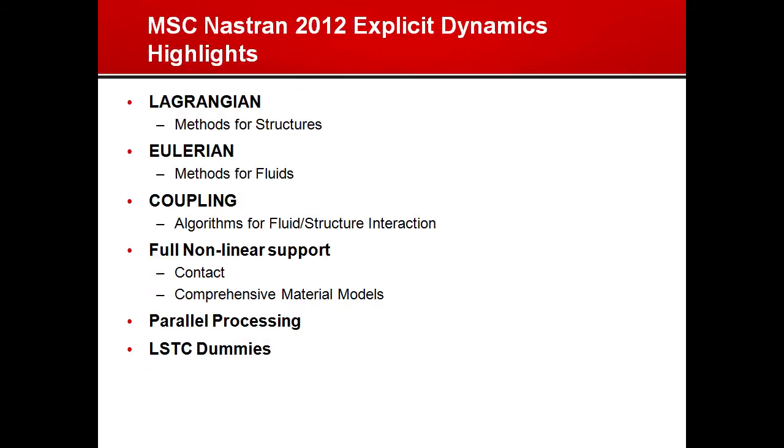So from a high level, within MSC Nastran we've got Lagrangian, typically used for structures, and Eulerian, typically used for fluids, and those fluids can have strength, which allows us to simulate structures with a fluid representation. We have some very powerful technologies that we call coupling that allow you to couple the Lagrangian and Eulerian solvers together and have an interaction between that fluid and that structure. That's a subject for a later webinar next month. Srinivas will talk about that a little bit. But it's a very powerful technology.